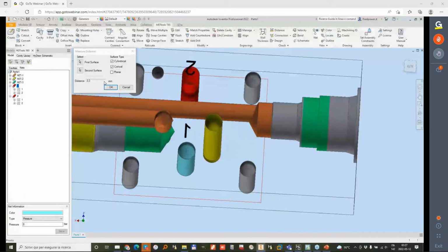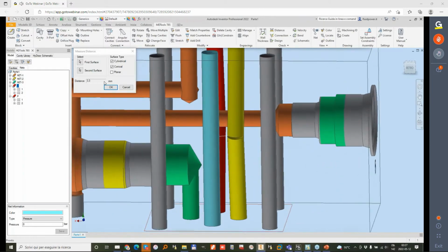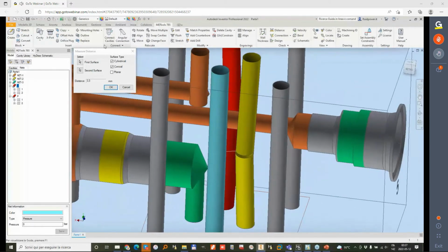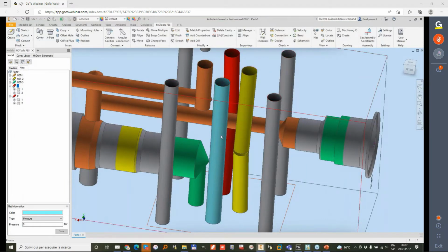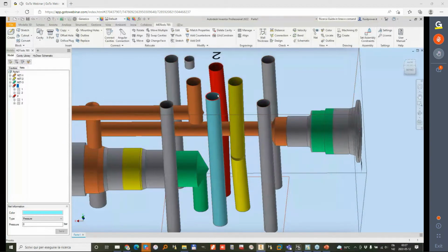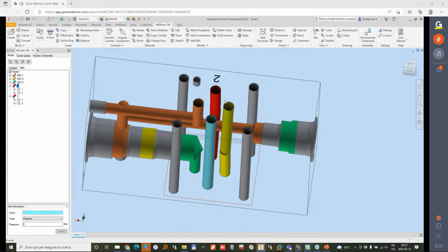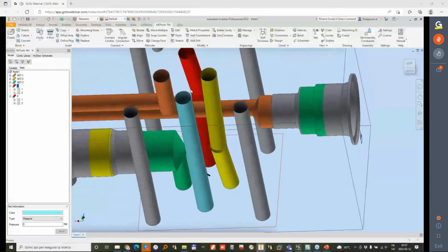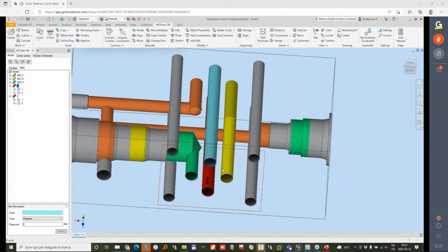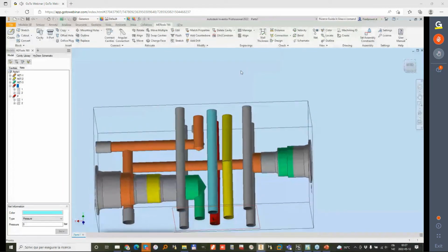It's not a lot, but for this kind of geometry, if the machinist pays attention, that should not be a threat. If we really want to be safe, we should also incline the tank line. I don't want to incline for this project because I want to explain another technique I frequently adopt for the machine drawing. So basically, this light blue connection becomes a pass-through bolt hole. I usually split the drill into two parts because I want both dimensions to be automatically made in the machine drawing, and we will see later in the machine drawing.